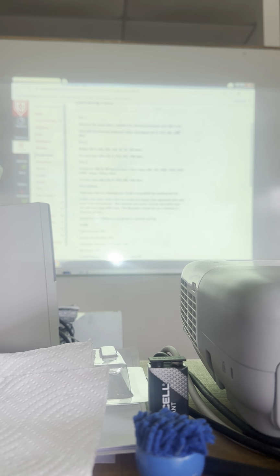Go to the lab. Part one, based on the circuit below, complete the following procedure and collect data with the following component values and measure IB, IC, VC, VRC, VRB, and beta. Can we do that? Absolutely. Now, part two, reduce RB to 40K, 20K, 10K, 1K, 100 ohm, and then take the same notes. Remeasure all of those IB, IC, VC, VRC, VRB, and figure out if beta changed.